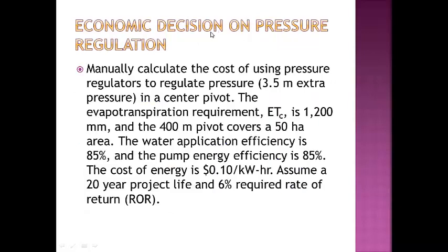Okay, let's look at a question that's often asked: should pressure regulators be used? Well, you'd think so, but the problem is they cost money, and also you have to pay for 3.5 meters of extra pressure in the center pivot. So let's look at a practical question.